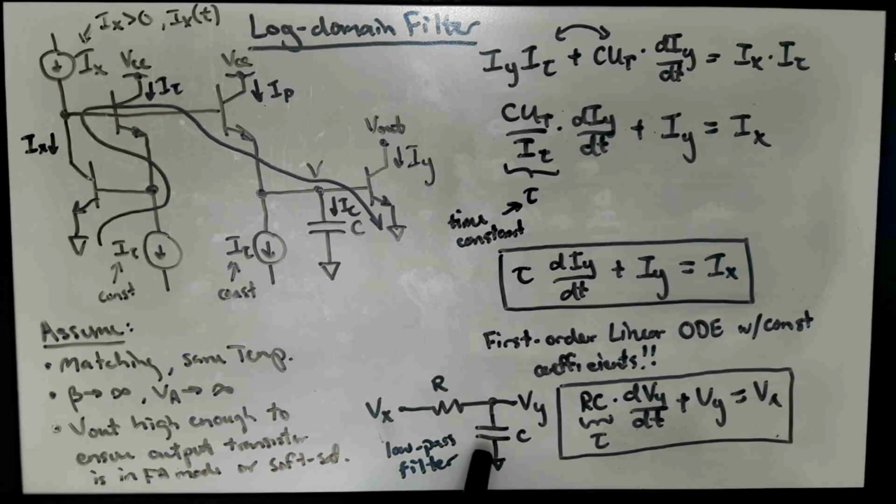So capacitors are pretty large devices, but they integrate pretty well, because integrated circuits, as we'll learn in a while, are basically fabricated by having a thin layer of conductor separated by a thin layer of insulator separated by a thin layer of conductor, and that's a formula for making a pretty good capacitor.